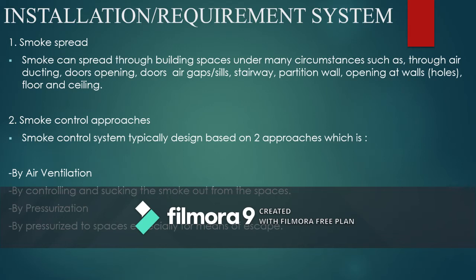Second, smoke control approaches. Smoke control systems are typically designed based on two approaches. First, by air ventilation, by control and sucking the smoke out from the spaces. Second, by pressurization, by pressurizing spaces, especially for means of escape.